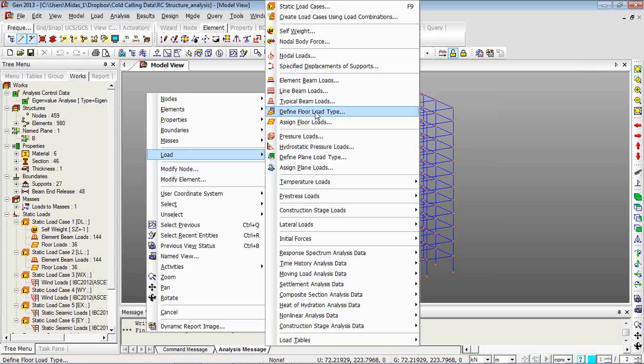the slabs can be modeled in, let's say, 2 ways. You can either model them as plate elements or in the form of a rigid diaphragm. I'll show you shortly. The results will be almost the same, but I'm currently not modeling slabs. If you want, I can hold a special webinar training session for you, and we can go on with that topic.